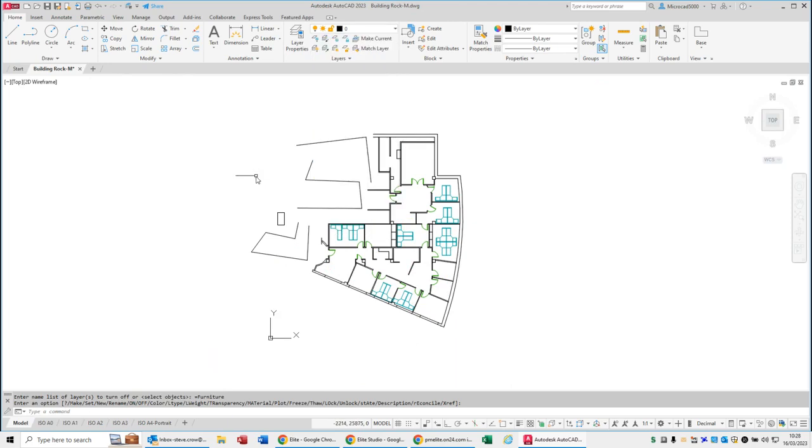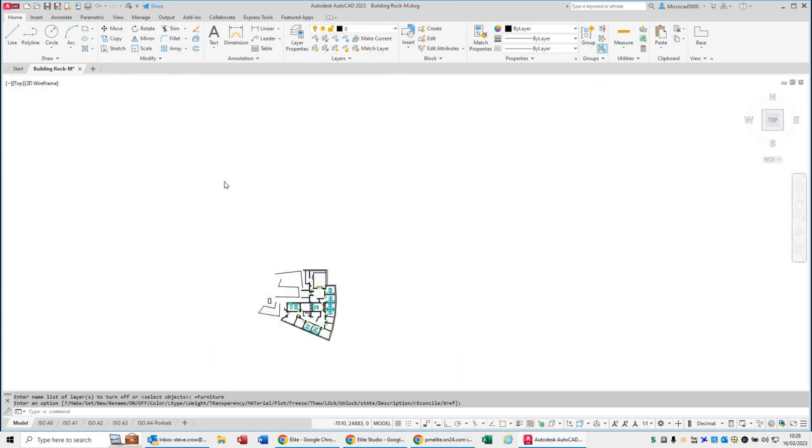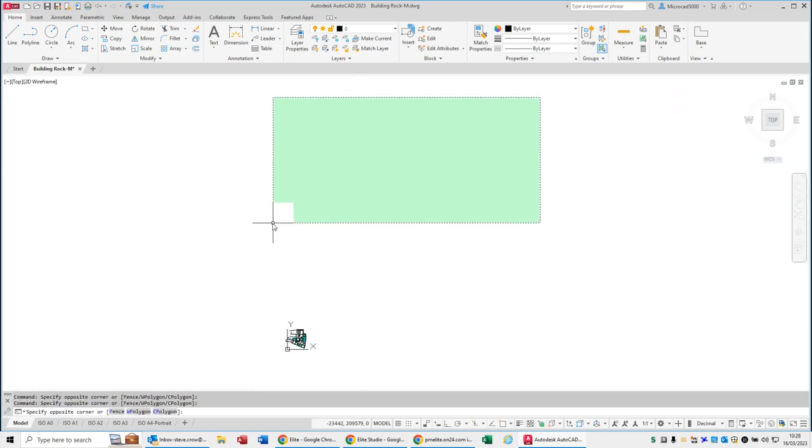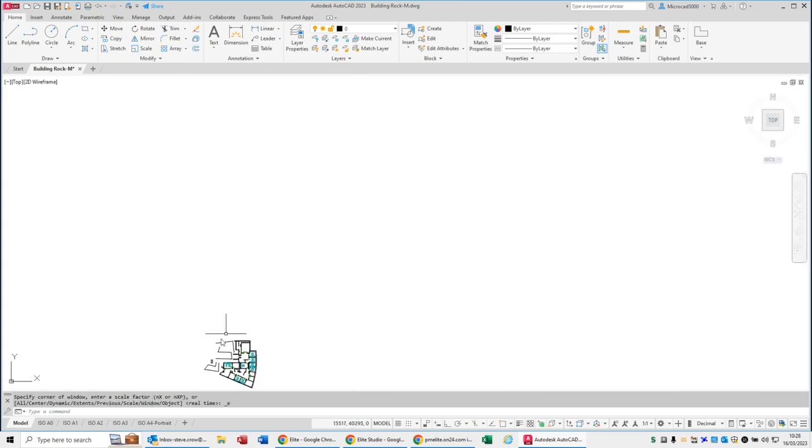If I turn it off and double click my roller, my drawing does that. Now, if your drawing shrinks down the screen like that, you think to yourself, there must be something over here somewhere causing that. I'm doing an erase crossing, and there's nothing there. Double click my roller, and it does that.